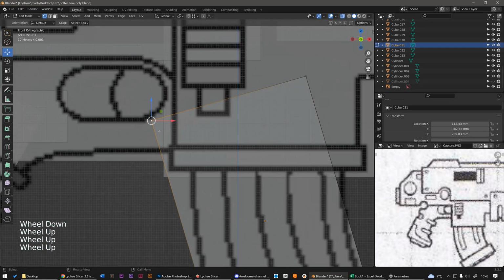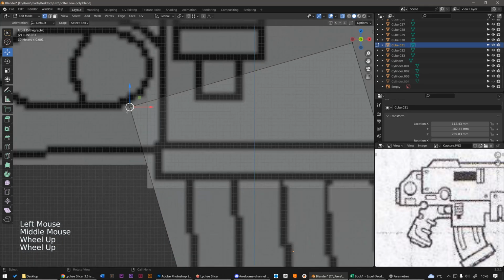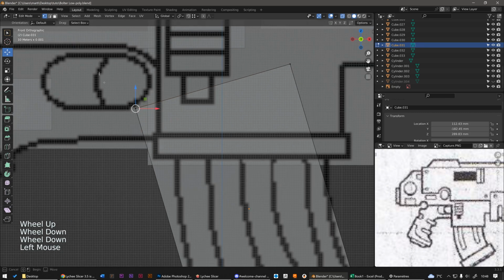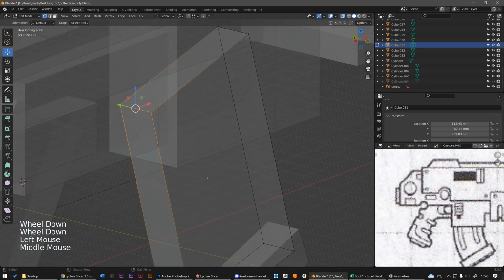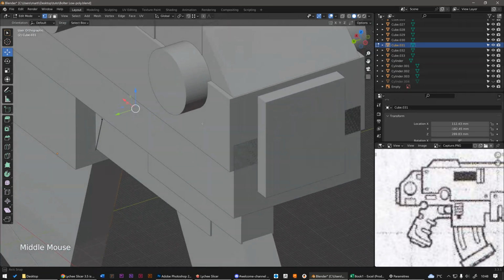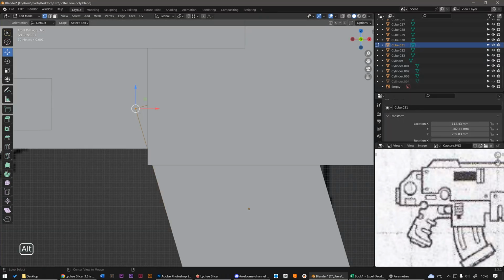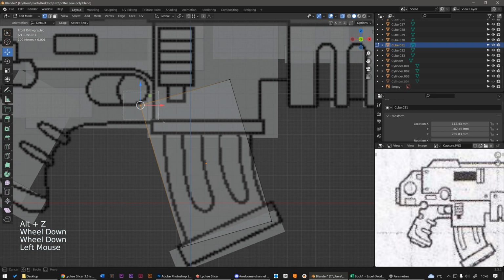Note by the way that, to be able to select background vertices, like this one, you must be in transparency mode. There if I use the rect box I selected the 2 vertices. But if I had not been in transparency mode, let's start again, we can see that the vertex behind has not been selected. So we very often work in transparency mode.